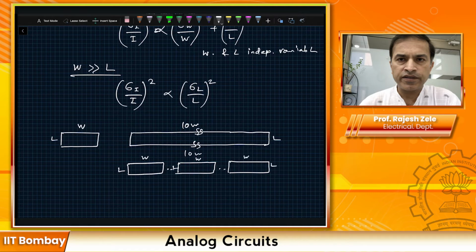What I suggested last time was that this would be preferred because you would have the exact same statistical behavior on your W's and L's. You may be able to get a very similar result over here because finally you can chop this transistor like this to make 10 units, and then statistically you can get pretty much similar behavior.